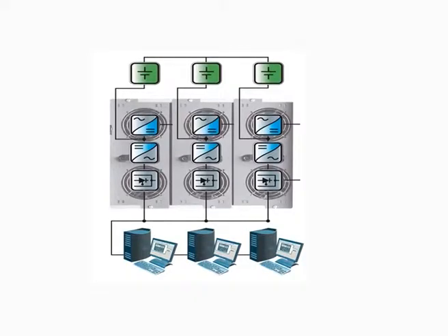It first converts the voltage AC into a battery compatible low voltage DC using circuitry called a rectifier. The rectifier supplies power to the inverter, the next stage, in addition to charging the batteries. This direct current is then converted by an inverter back into highly controlled and regulated AC.